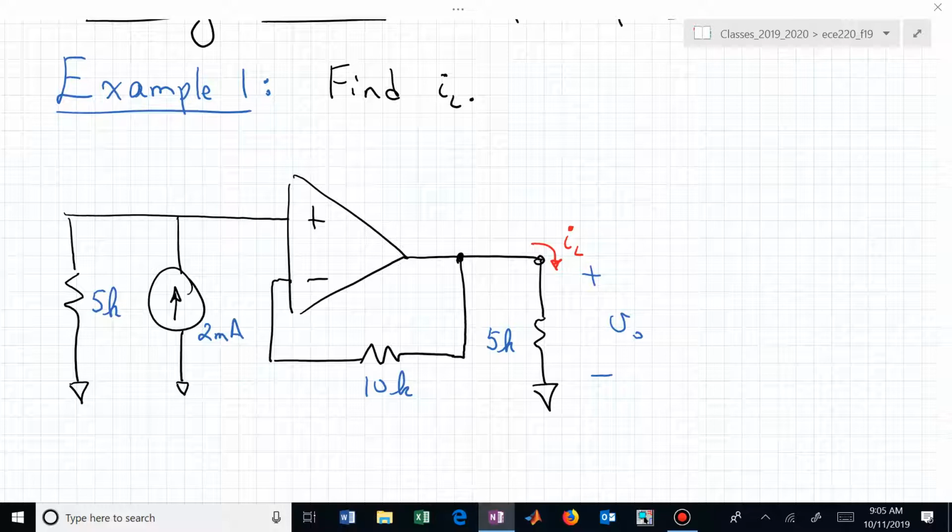It has, and what's missing here that's implicitly assumed from this circuit? What is missing? And now you might ask, will it actually function? That's what I'm asking behind that first question. Will this even move or do anything? Given the way I've drawn it here, what I am not drawing explicitly are the power supplies, the rails that are supplying this. So you would have to energize this with a voltage at the positive supply pin and a voltage at the negative supply pin, and that negative supply pin just needs to be less than the positive supply pin. It could be grounded, or our reference node. It could be just less than, but traditionally it's 0 or lower.